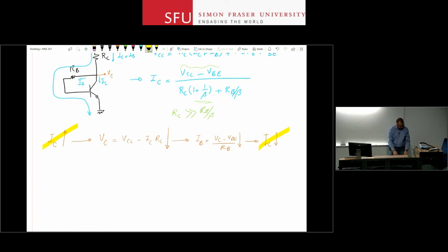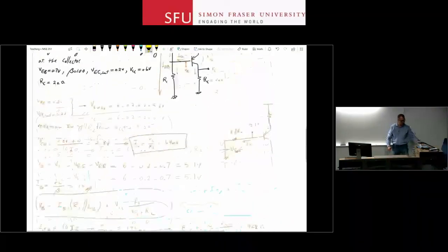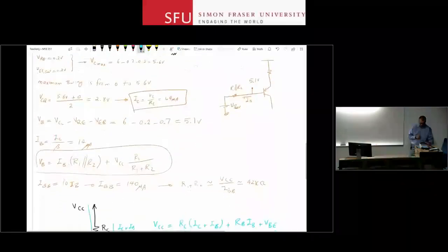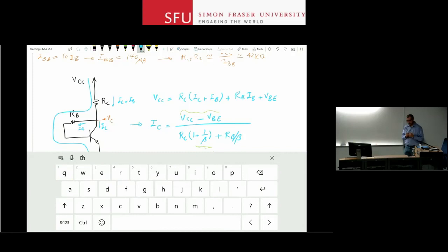And these two techniques are basically your two biasing techniques that you can use for your common emitter, common base, common collector stages. However, if you're using the H biasing, you get your original stages back, right? So you can just separate the biasing and then look at what is happening between the biasing network at the input and maybe the load, and say this is my common emitter stage or common collector stage, and so on and so forth. With this biasing, you cannot do that.